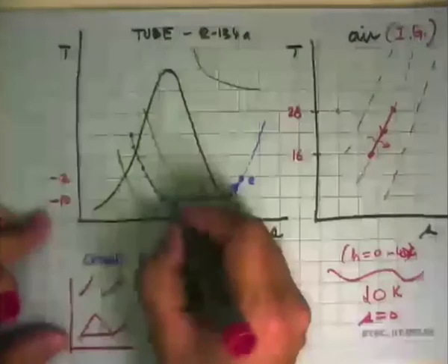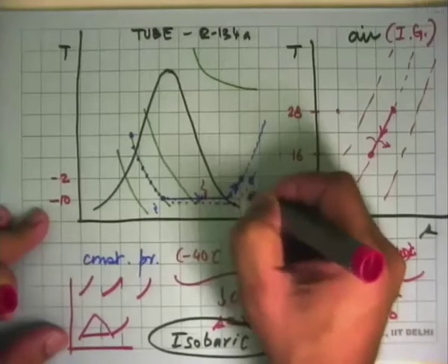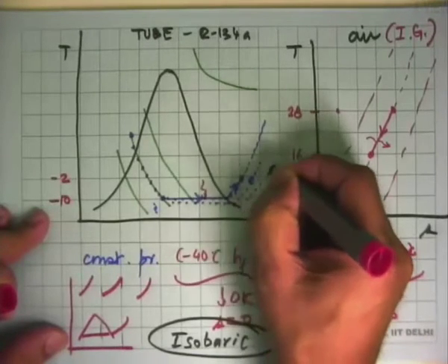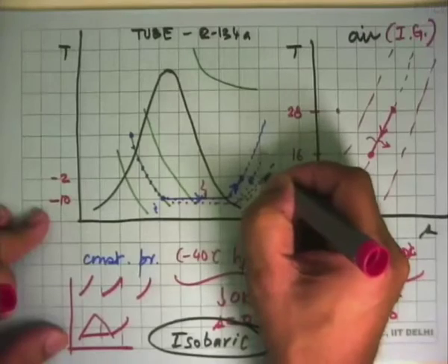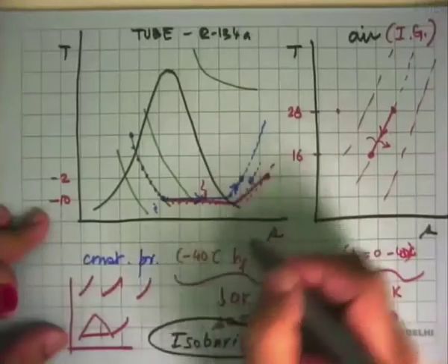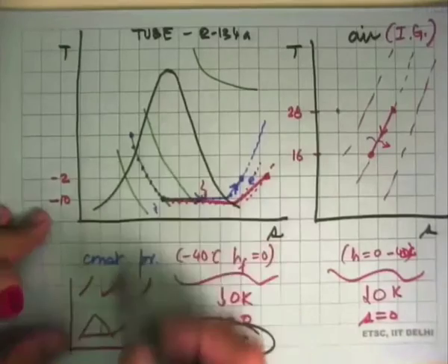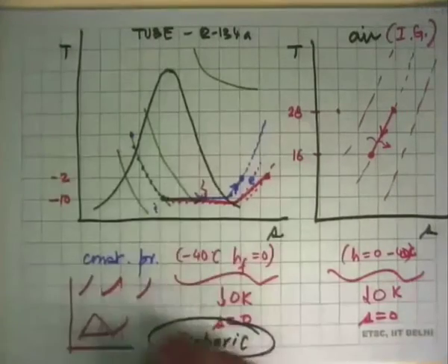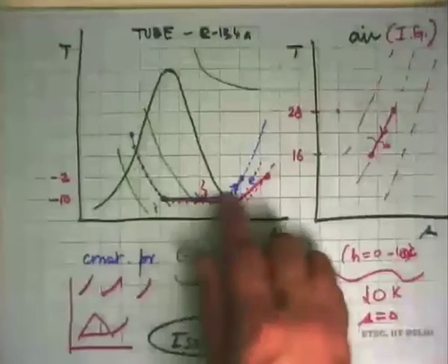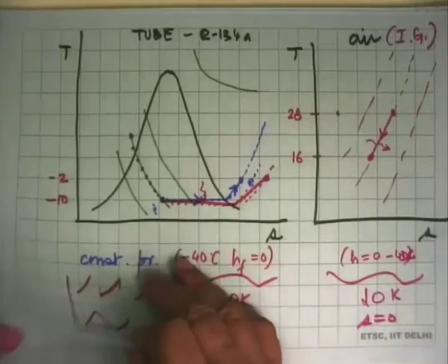It will be that as it keeps going, there is a slight pressure drop all the time, it comes over there, then it would have gone along this, but there is a pressure drop, so the lower pressure isobar is there. So from here it will go and finally end up at this place. So the real substance will go like that, and the pressure here will be less than the pressure here is less than this pressure. But in the analysis that we do, if that is not given, we assume it to be a constant pressure heat transfer process. Okay, so that is the idea of a heat exchanger.